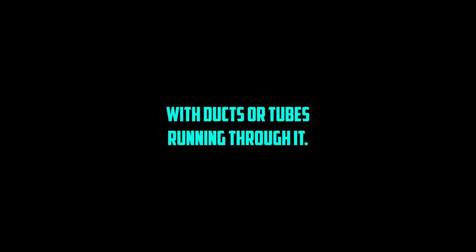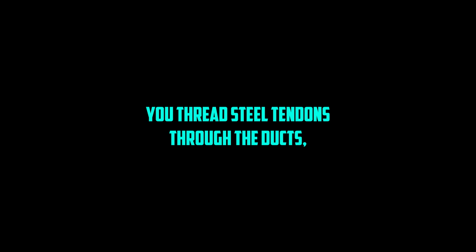Okay. And post-tensioning. That's often done on site. You cast the concrete with ducts or tubes running through it. After the concrete gains strength, you thread steel tendons through the ducts, stretch them with hydraulic jacks, and then lock them off with mechanical anchors at the ends. The ducts are usually then grouted up for protection and bond.